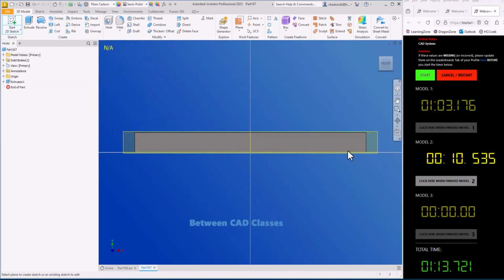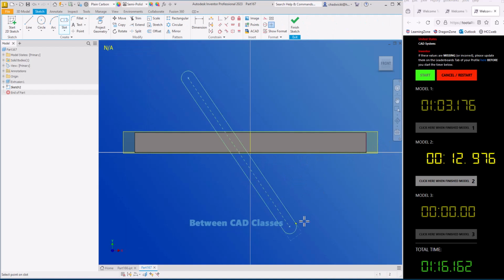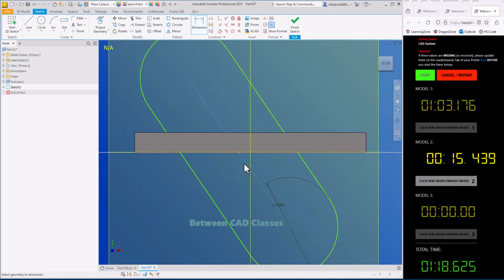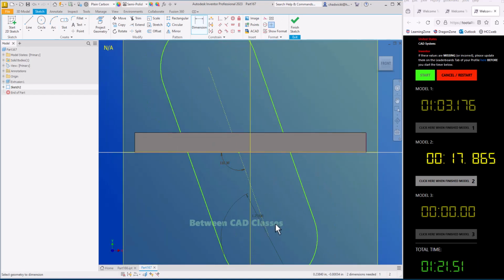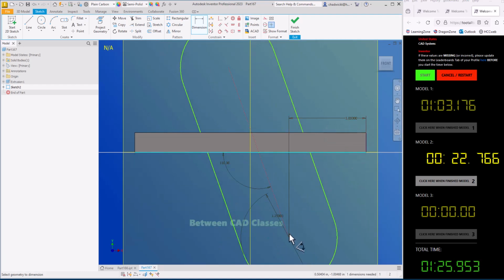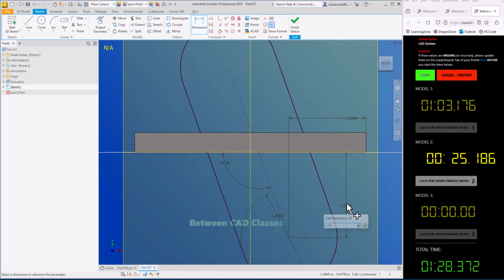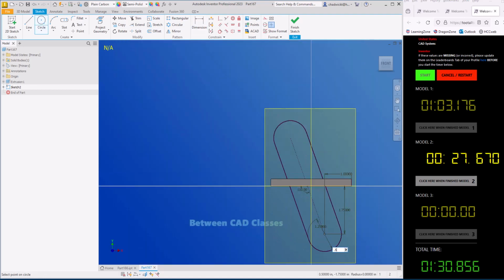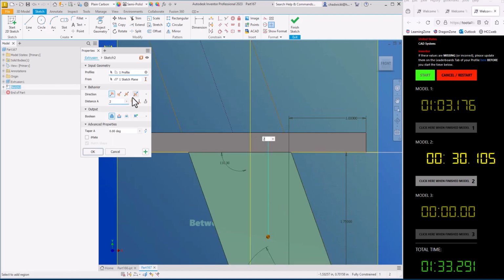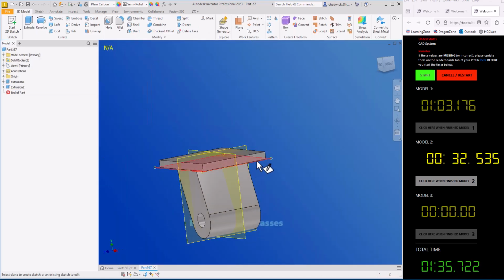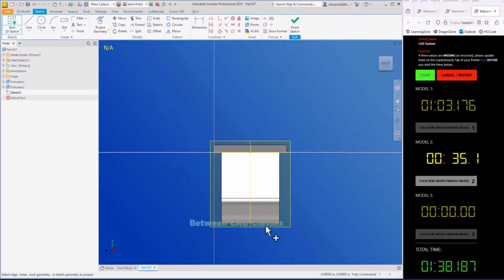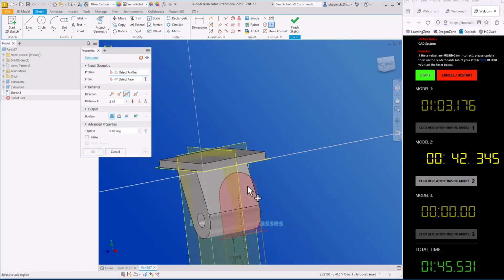One thing I found is sometimes I'm doing things so fast that Inventor isn't keeping up with me. So while I think I could go faster, I'm not sure if Inventor would honestly let me go any faster. But here you can see I started with a slot shape and I'm adding in some dimensions here to locate this feature, adding in a hole, and then extruding it symmetrically, and sketching on the edge here, and then projecting geometry with once again another keyboard shortcut, and then creating a slotted feature, once again with a keyboard shortcut, and then extruding this through all.